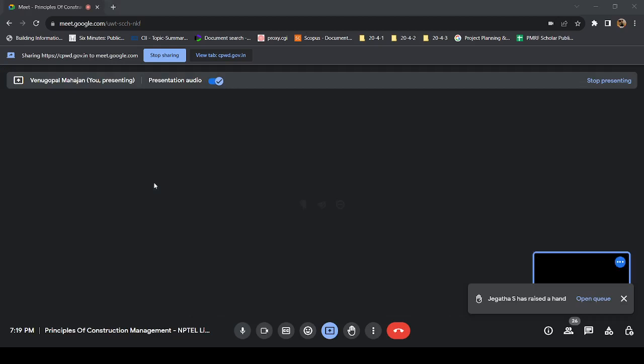So you can see that rates are given per square meter. All you have to do is fit in the values and multiply. 1.0 is your building cost. Building cost consists of your structures, foundation, basement floor, some systems like firefighting, fire alarm, and stilt portion. 2.0 is your services. Now, how do you calculate the services? Percentages are given, but on what part should these percentages be taken? It says percentage of building cost. We will see it in detail.